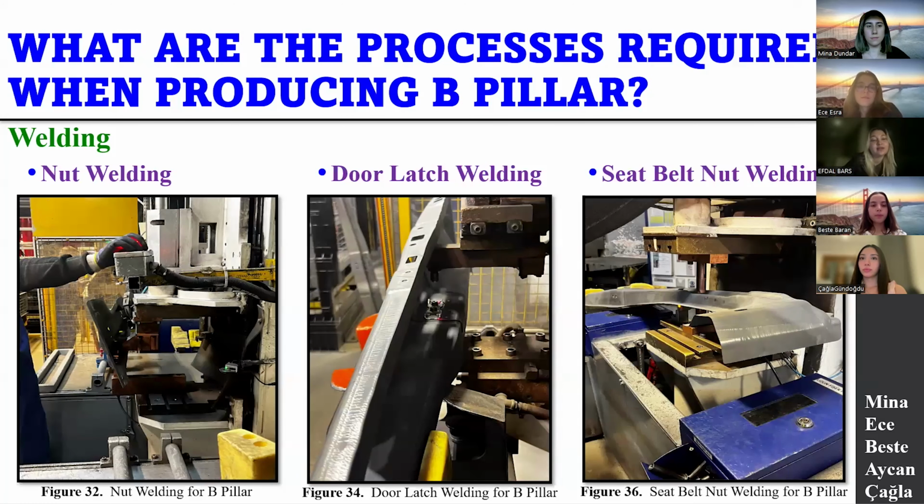Welding. Welding process is the fixing of two metals to each other by melting the metal by applying high current to the copper tips. The reason why tips of welding machines are copper is that copper has the ability to bring metal to melting point at high currents. And nut welding. It is the fixing of the nut parts, adhering to desired parameters during the welding process.